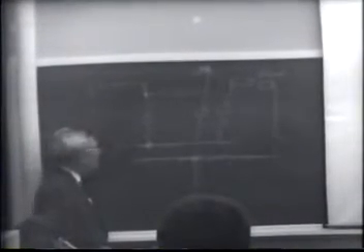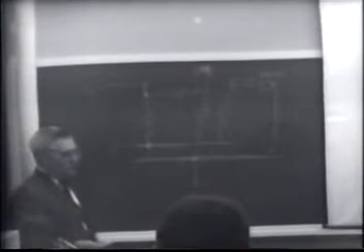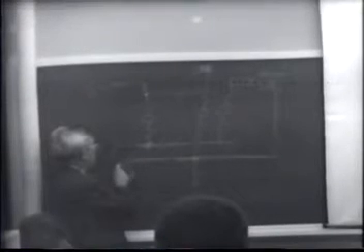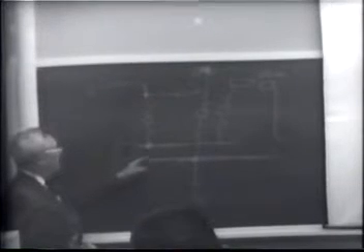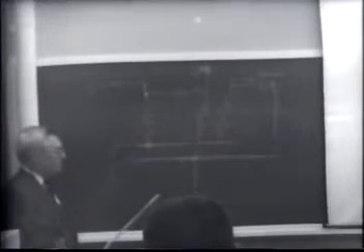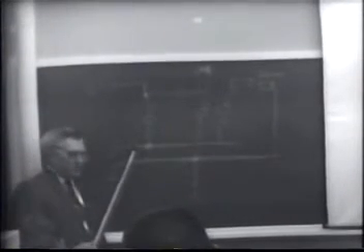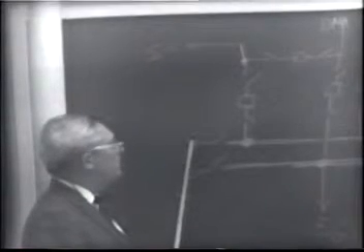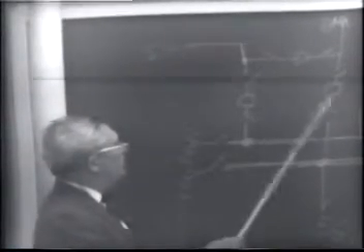This will be really what is called a modified breaker and a half scheme, because the design of this particular bus ties the transformers directly to the bus sections through an interrupting device which can interrupt magnetizing current or a small amount of load current. But in the event of a failure of the transformer where it has to be relayed and you have to interrupt fault current, you would have to relay all of the breakers connected to that particular bus. It would take one bus out of service with the transformer.